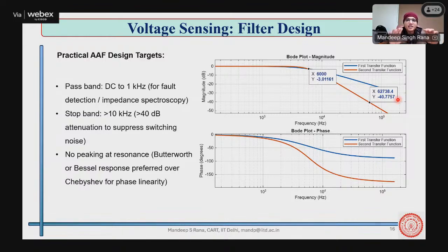Suppose there is a noise which is coming at 0.5 volt. You divide that 0.5 volt by 100. That much will be transferred if it is minus 40 dB. So you are actually making the noise 100 times smaller. Good part is, already over the main signal, the noise would be a small number. So if you make it 100 times smaller, it nearly goes away.